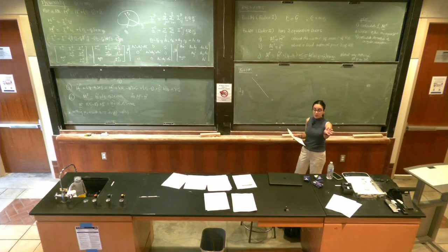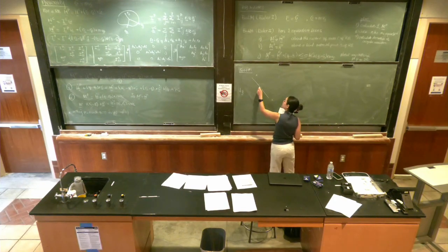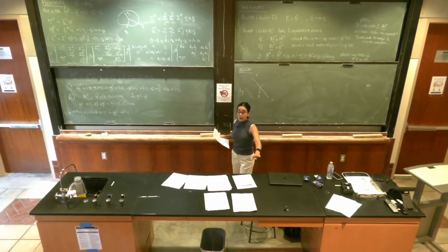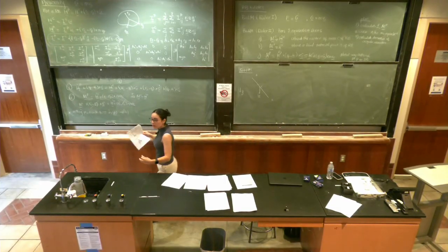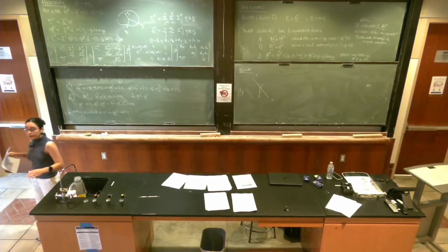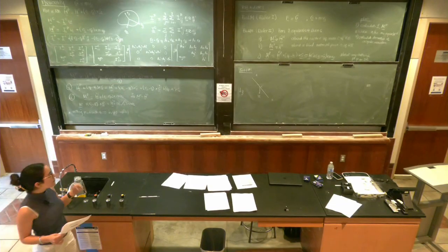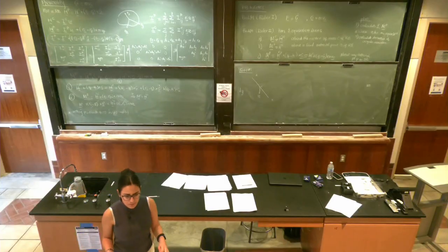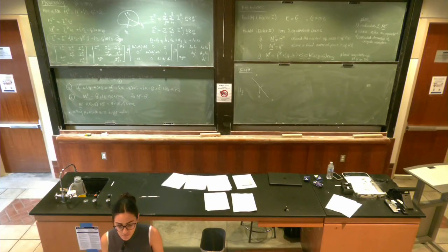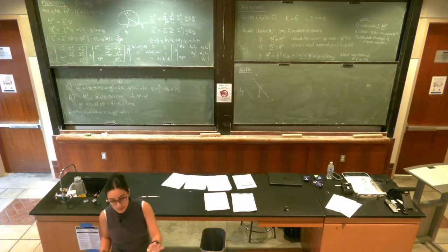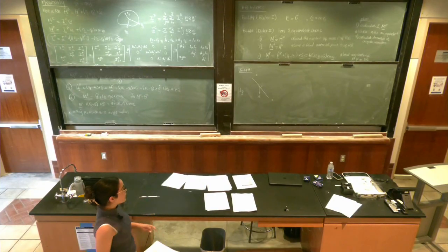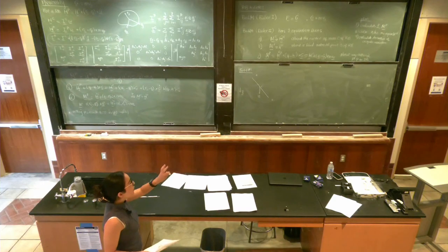The weight at which point? Center of mass. At the center of mass. I'm going to call the center of mass of this rod C. So, great point. Now we're talking about rigid bodies. The point of application of the force matters, right? It matters if the weight applies at A, B, or C. I can show you that the weight is always going to apply at the center of mass, and it's not going to have a resultant moment. So we can show this. Remind me to do it after we finish this problem. So for now, we have the weight acting at the center of mass.